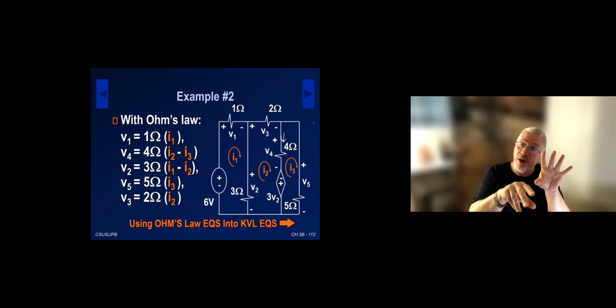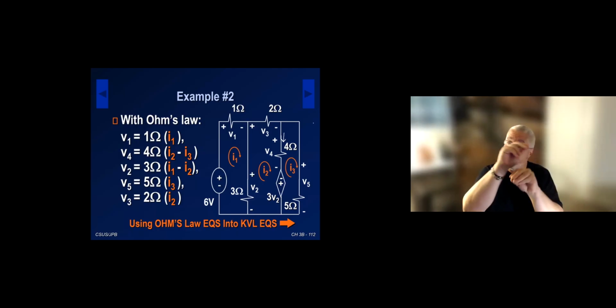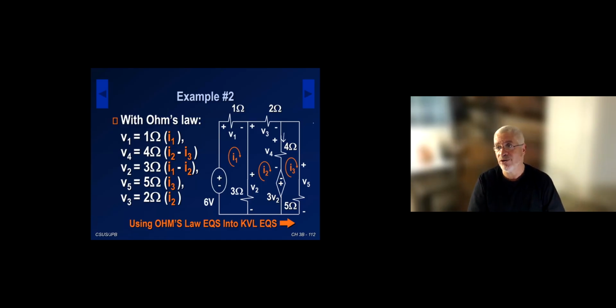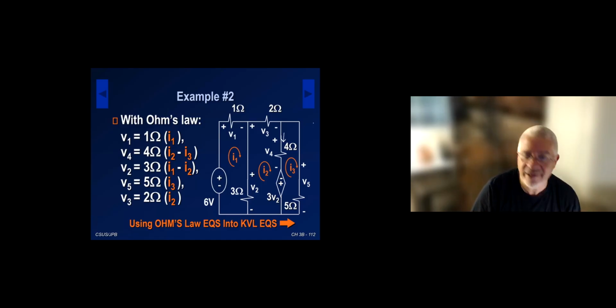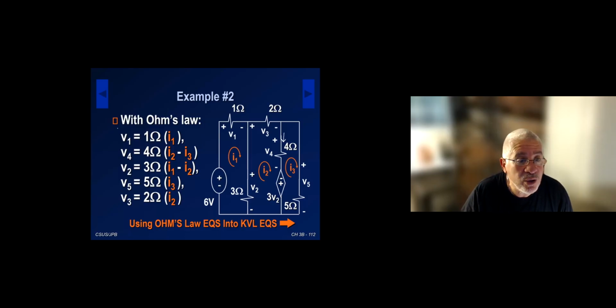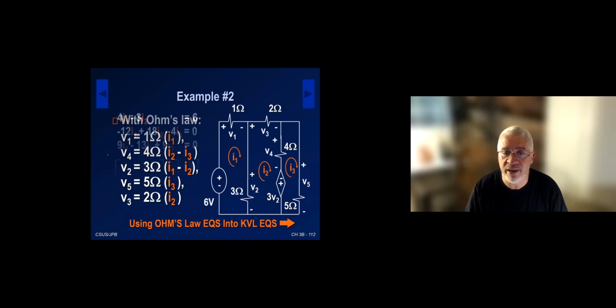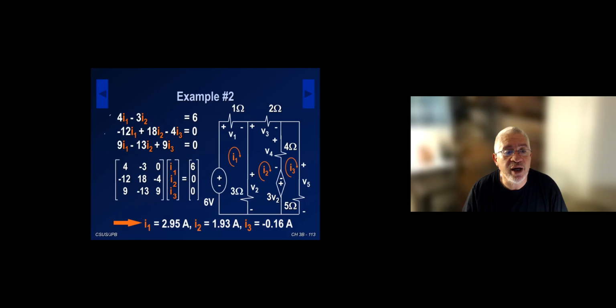It's when we do Ohm's law, then the mesh currents and the voltages where we put plus and minus, everything synchronized to get you correct solutions when you satisfy the passive sign convention. So we're going to take those 5 equations, put them in the 3 KVL equations and collect terms. Collecting terms makes it easier because you don't have to put things under the same denominator. So we get 3 equations, 3 unknowns, and I'm expecting you to use a calculator. And then essentially we get out 3 mesh currents.